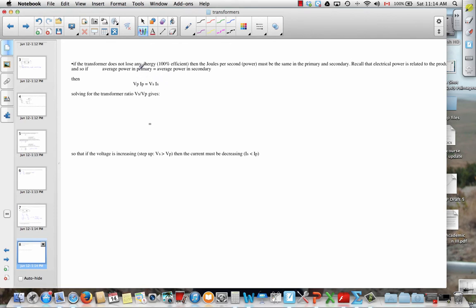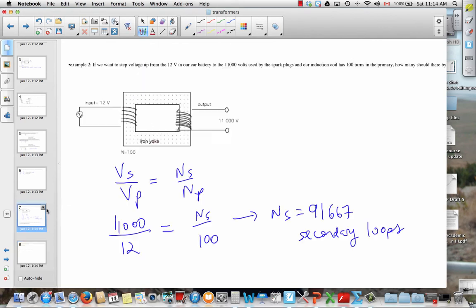What I'm trying to say is the application of the transformer equation to this circuit is appropriate, even though it's powered by a DC, because of the clever use of that switch in the ignition circuit.